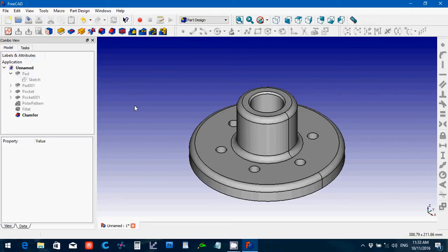And then we're back to where we should have been. Don't ask me. FreeCAD wants you to do that as the very last step. Going in and modifying things will almost always break the fillets and the chamfers for some reason. Sometimes it works. Sometimes it's just fine. But sometimes you're going to have to go back and redo it. And it wasn't that hard.